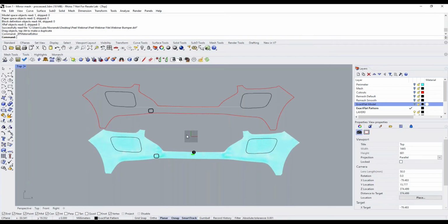Yeah. So I think it really depends on the type of part that you're working on, right? I mean, if it's complicated, then you may mirror it. You have to make a balance between scanning time and post-processing time. If you scan the whole part, perhaps your post-processing time is lower, but that depends on the complexity of the part that you're scanning. And there's a lot of different factors. The material that you use would have a role in that as well. How stretchy is the material? How expensive is the material?